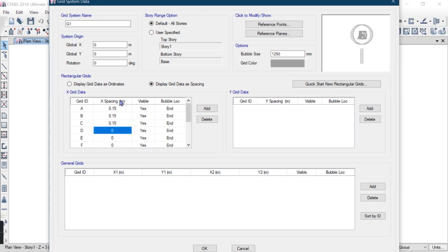The span between these two columns would be like 3 meter, but I am taking 4 meter here because it is a flat slab. A flat slab is provided where the span between the columns is higher. So here the next is 0.15. I know you are not getting this 0.15 in 0.1, so you will see further on why I'm taking this 0.15.